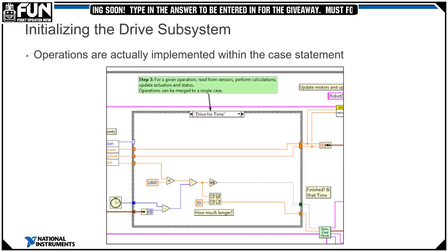Because we definitely don't want to get close to that safety timeout, because if we miss it due to execution time or your vision processing loop is slowing everything down, if we miss that safety time point, it'll actually time out all your motors. So we definitely want to make sure we're updating it frequently enough to catch that safety timeout, basically. We're just playing it safe here.